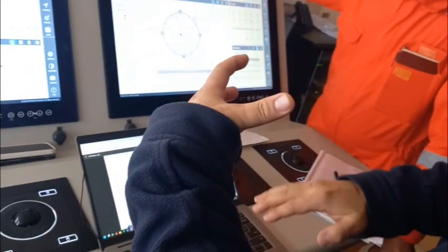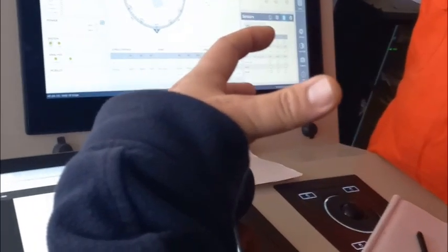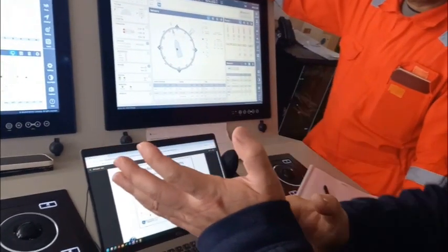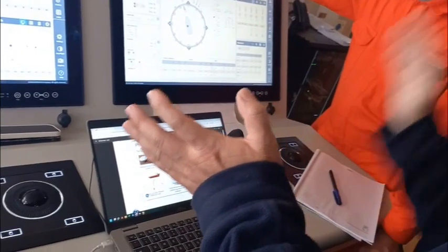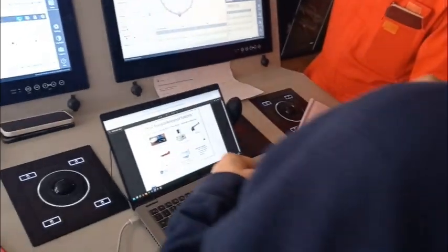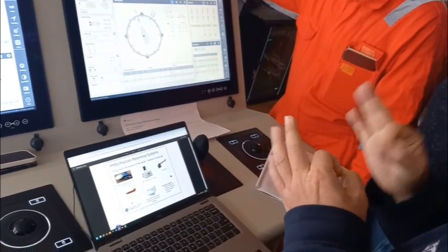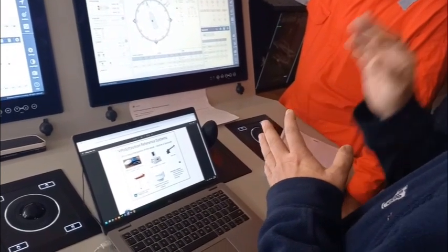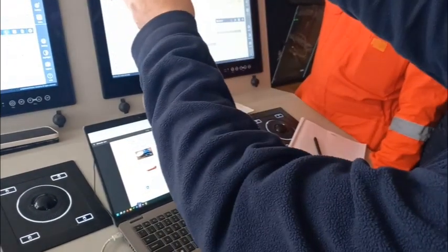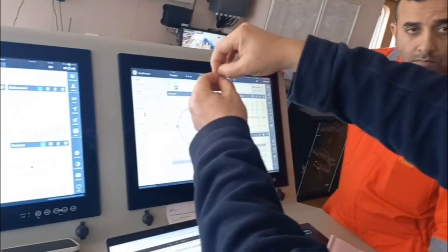Azimuth. This angle is, no, it will have two angle outputs. One is azimuth, another is elevation, and then another is the extension. The gangway can be extended, right? So extension, azimuth angle, and elevation angle. These three are analog signals. Plus, when the gangway is deployed, the end of the gangway will touch the other vessel or platform.